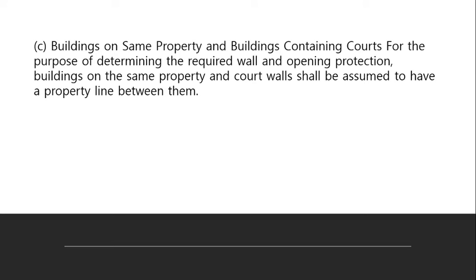So let's proceed to buildings on same property and building containing courts. For the purpose of determining the required wall and opening protection, buildings on the same property and court wall shall be assumed to have a property line between them.